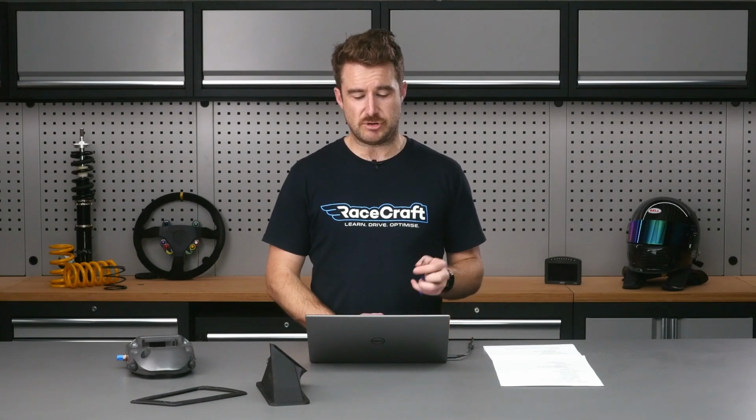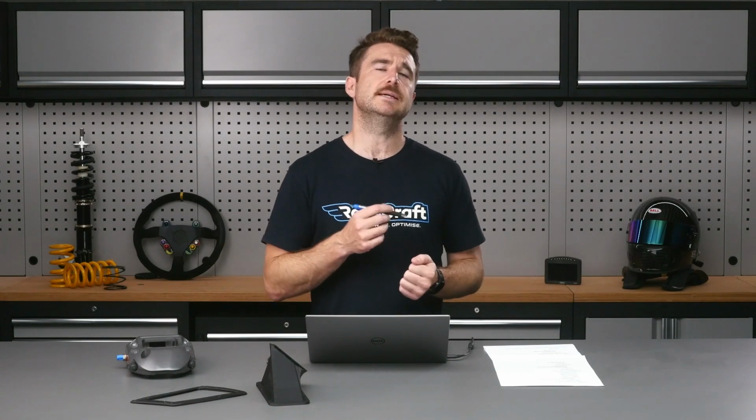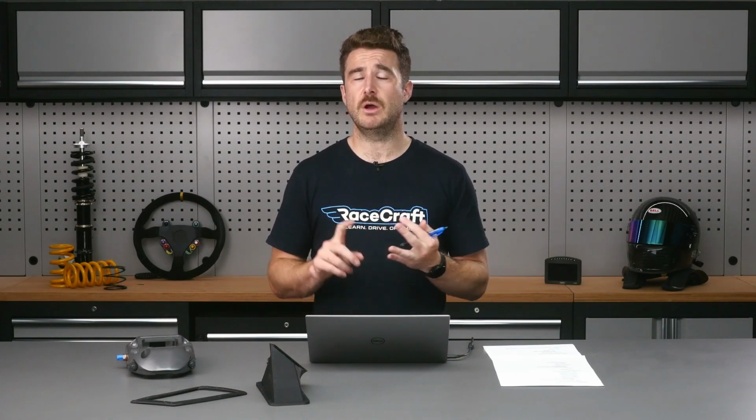So the last thing I wanted to go through today, looking at some of the driver analysis, was the idea of telemetry. I spoke a little bit in the last webinar about the difference between telemetry and log data. Essentially, telemetry is data that we're getting live off the car as it's heading around the track, sent back to us in the pits over a mobile signal, like a 3G or 4G signal, or by radio telemetry. All of that data is coming in live. The log data is what we download when we plug into the car and pull the data down. There's a bit of a difference in those two pieces of data.